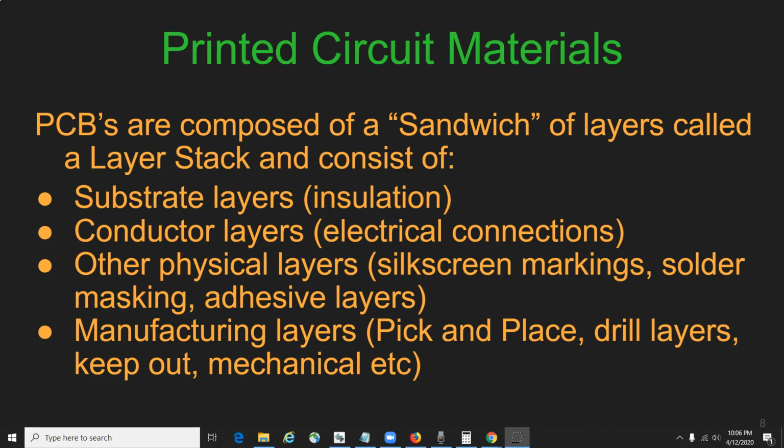If you see the silkscreen markings, they are basically used on the component side to identify the components, their test points, part numbers of components, warning symbols, or company logos, or manufacturer marks, etc. These silkscreens require specially formulated inks, standard colors, for example, black, white, and yellow.